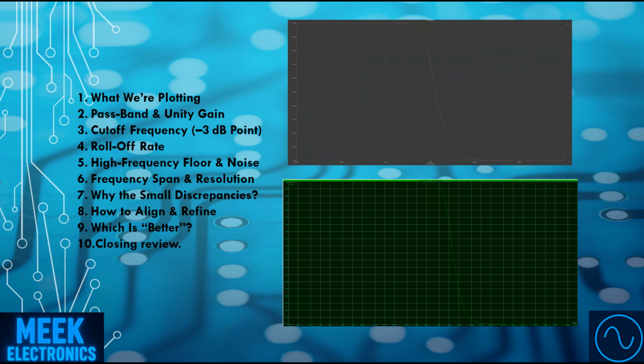5. High-frequency floor and noise. At the high end, Proteus bottoms out around -80 dB, which is really the SPICE solver's noise floor under default tolerances. Altium shows a smooth drop towards 0. Its graph simply stops plotting points once they're exceedingly small.